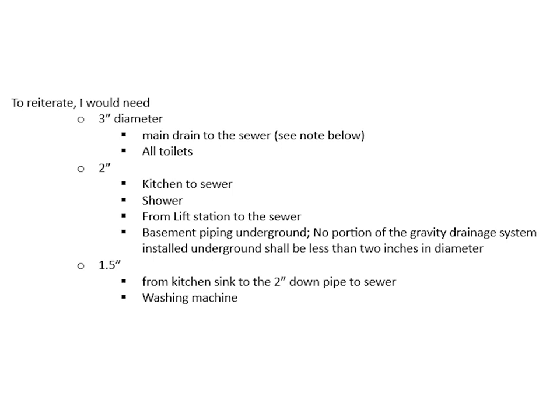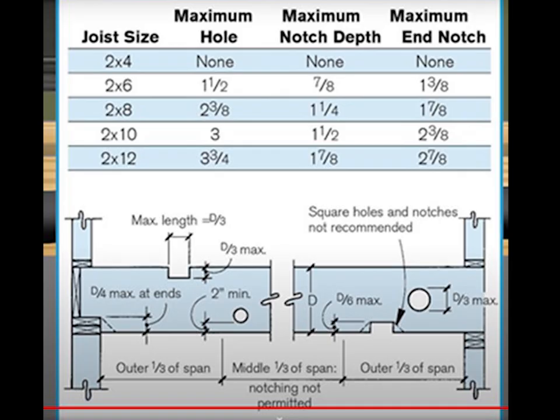In addition, the code specifies that tees on the drain pipe angle from level to down. For slope, horizontal drain pipes slope as a function of pipe diameter. Less than 3-inch diameter, 1/4 inch per foot. 3-inch to 6-inch diameter, 1/8 inch per foot. You are allowed 5 degrees per fitting off of vertical. For pass-through holes, use a 2 9/16 inch drill bit for a 2-inch pipe. This allows for pipe outer diameters of 2.375 or 2 3/8 inch. Observe these guidelines for boring through beams.